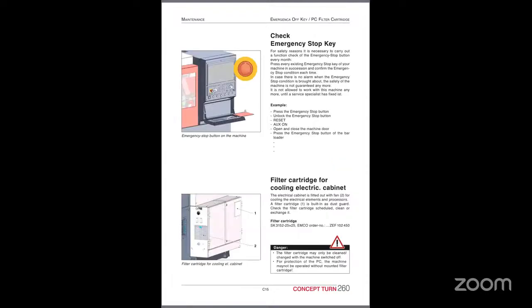Check the emergency stop test. This is very important. Test this emergency stop monthly. Machine on, spindle start, emergency stop press. The expected result will be spindle will stop immediately, axis will stop, and drives disabled.